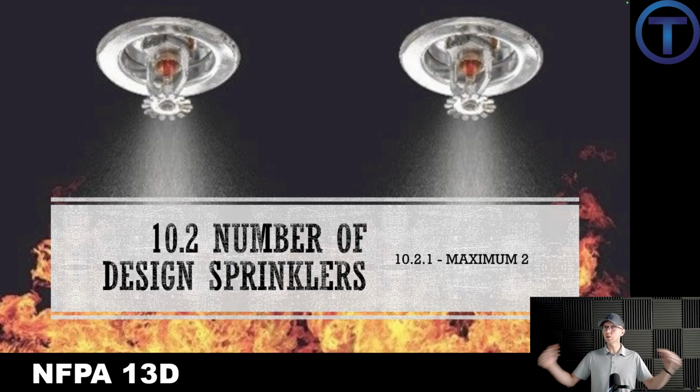If you get too many heads open at the same time, then the system won't be able to deliver enough water to do the job. So generally, in any room or compartment, you're going to have one head, and when that goes, it should be enough to cover the fire-affected area. Now, you get into larger rooms or compartments, and you can start to add, but they say, in general, you'd want to have only a maximum of 2.